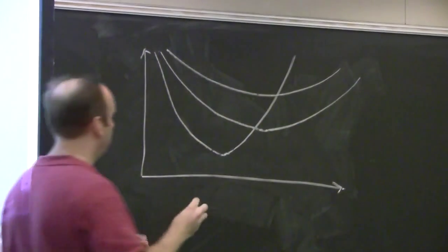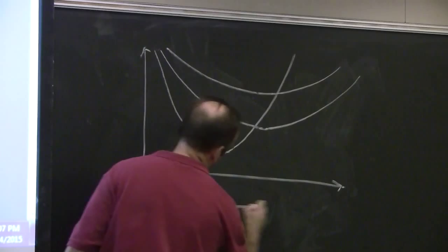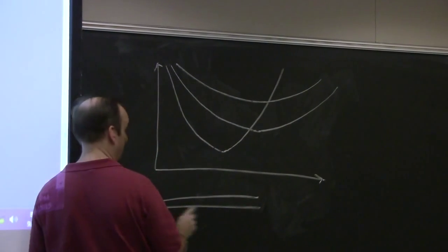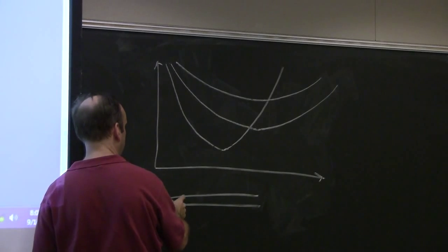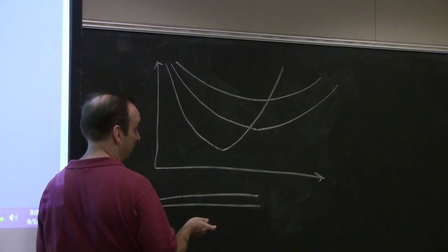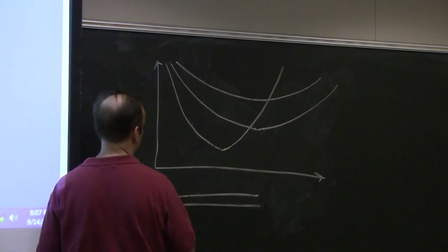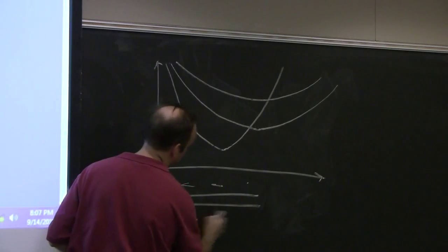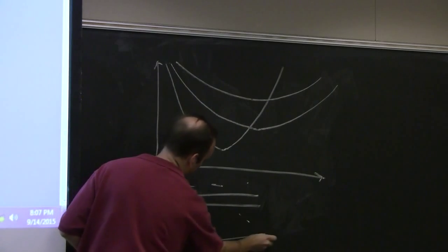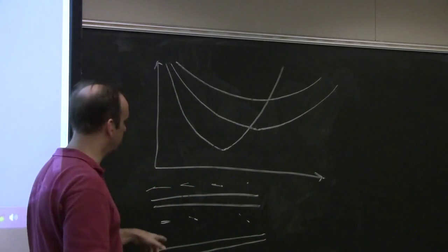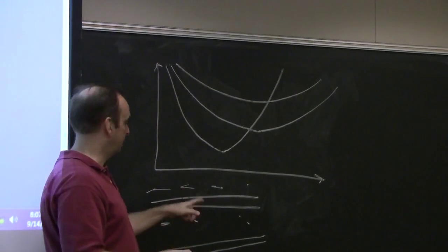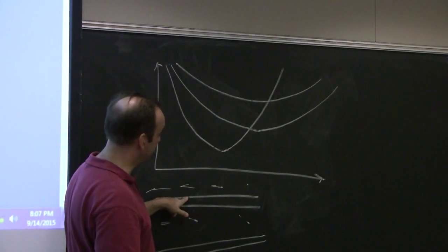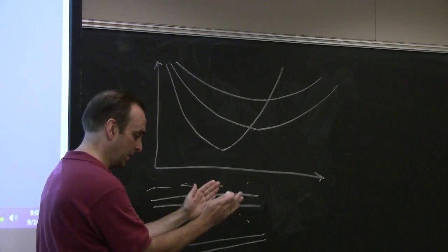And the other thing they do is, remember, most boards are multi-layers, right? So the best thing to do in a high-performance board is to put a power layer and a reference layer, not ground, adjacent. And then you have a signal layer where you've got some signal traces up here and some signal traces up here, and then you have another sandwich. The beauty of this is, what is a capacitor? A capacitor is two conductors placed closely together. Well, it's very difficult to get two pieces of metal closer than that.